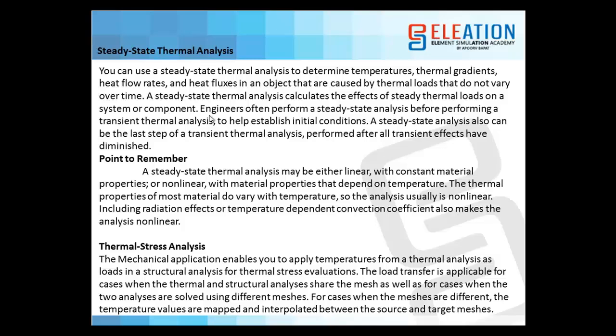Because of that friction, temperature is generated on the disc brake, and that temperature, how does it get transferred to a hub or knuckle, and what will happen to a hub and knuckle at that particular temperature, or you can say, what will happen to the lock nuts at that particular temperature. So we can perform two types of analysis in thermal.